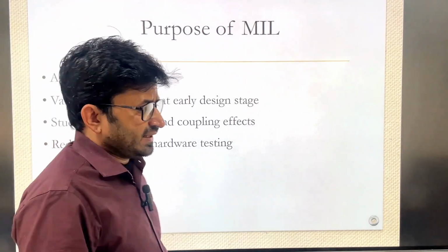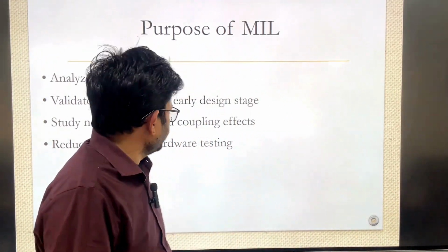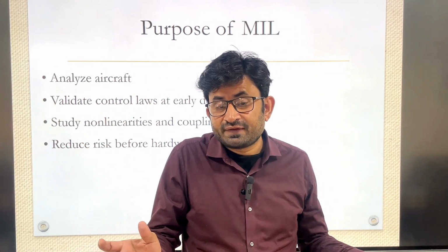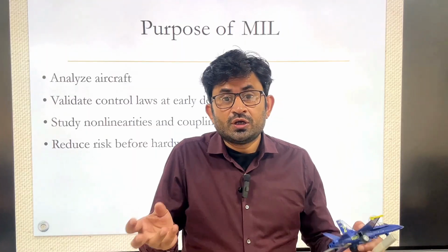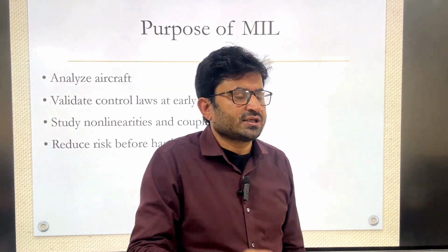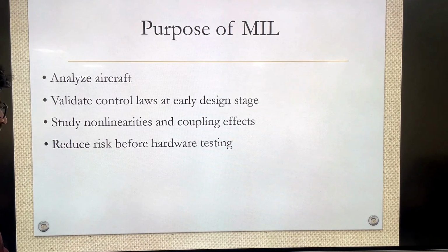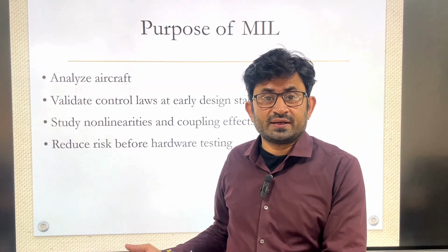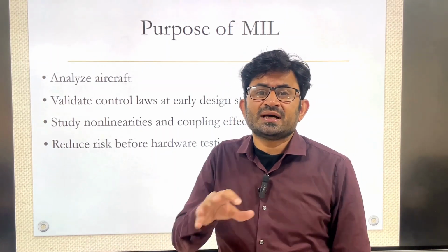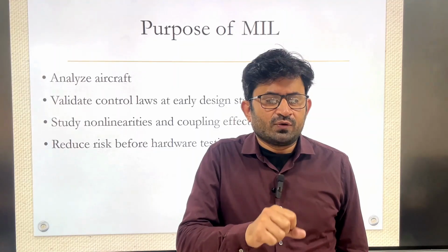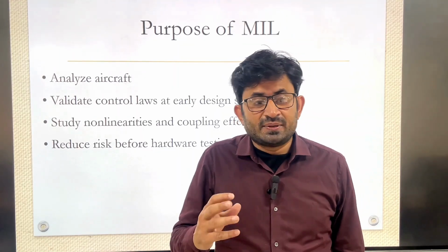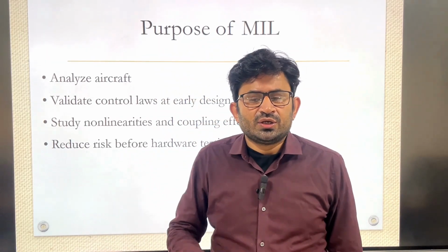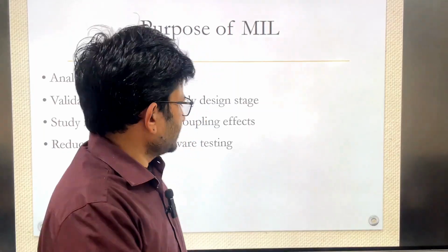And then if any other non-linearities are there, you can study them. For example, if you are landing the aircraft, you can model the ground effect, or if you are designing a VTOL, you can have a non-linear effect during the transition. So these things you can model and test. Okay, and of course reduce risk before hardware testing. Since there is no hardware involved in MIL, whatever you can do is in the software only, and whatever results come, you can correct based on the desired result. If you are not getting it, you can tune the results, change the parameters, and do so many analyses. Okay, so it is cost effective.